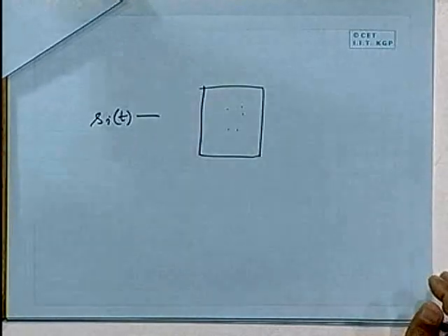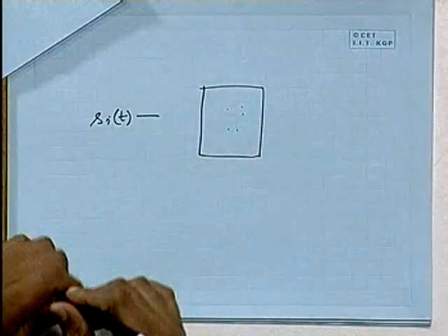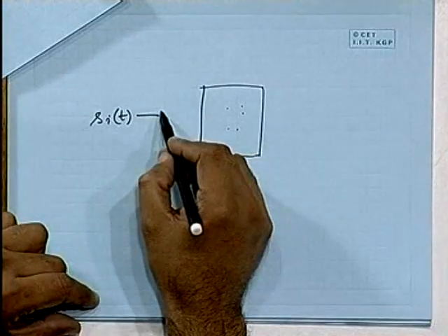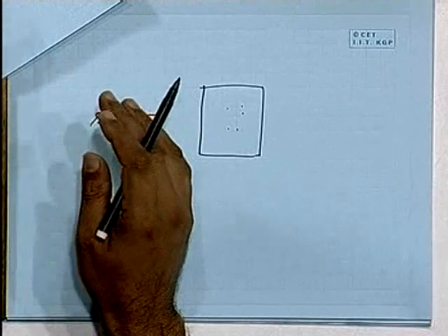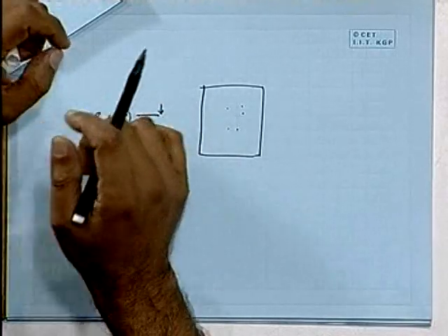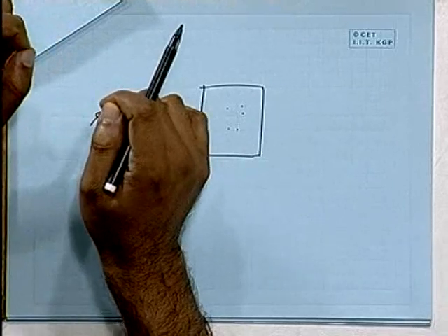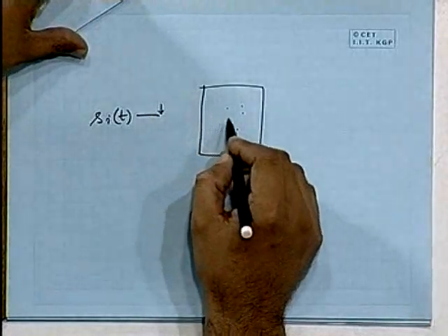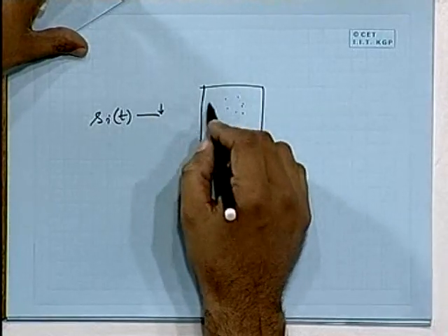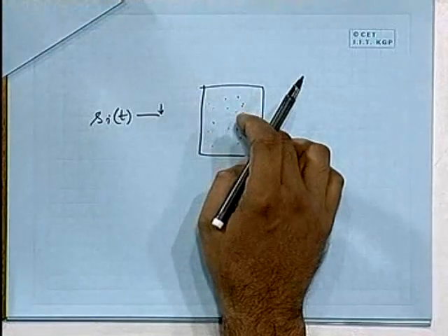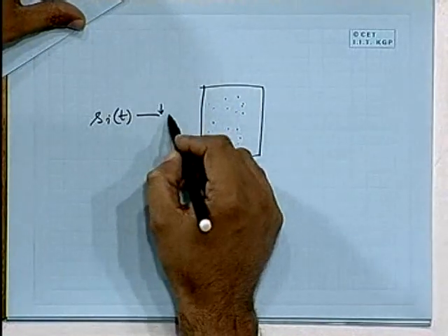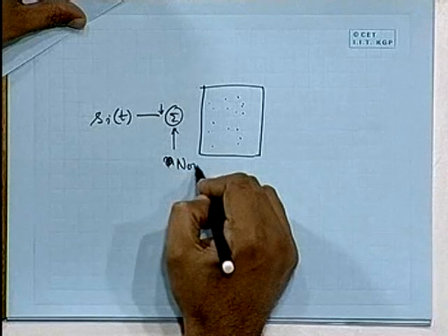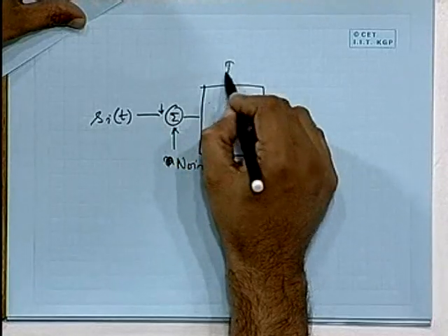Now coming back to our modeling. The LNA faces the first signal and tries to amplify it. The signal which reaches the LNA may have some noise because of the other RF portions beforehand, like the antenna matching unit, etc. Still, those are usually smaller for a good choice of components, and the LNA generates thermal noise from all dissipative components. We take them out and say that here is an equivalent noise due to the LNA, and this LNA is an ideal LNA.